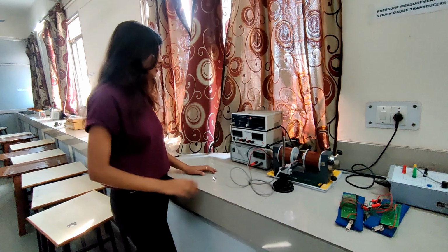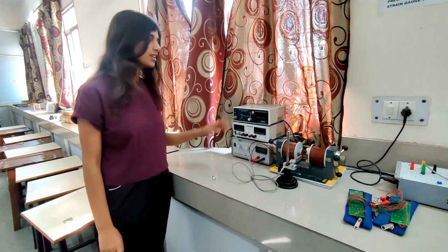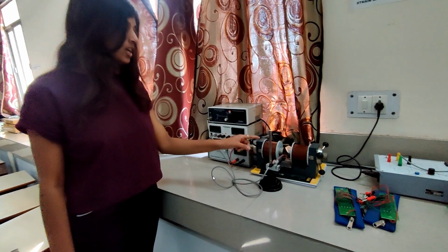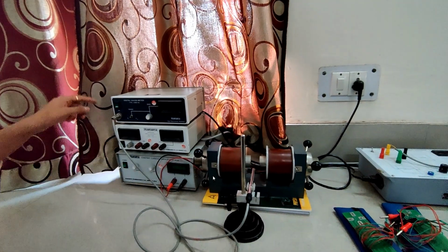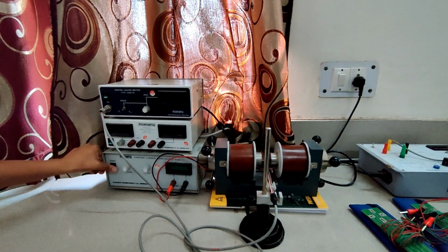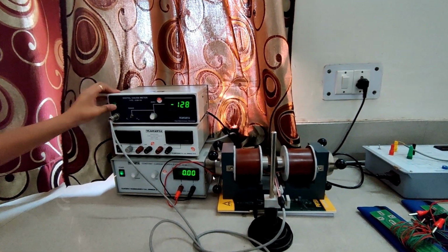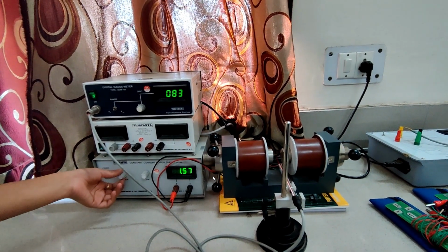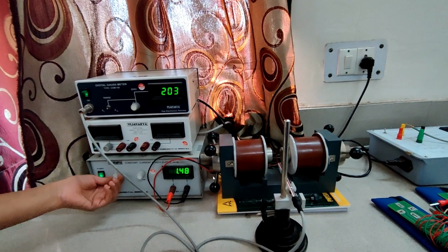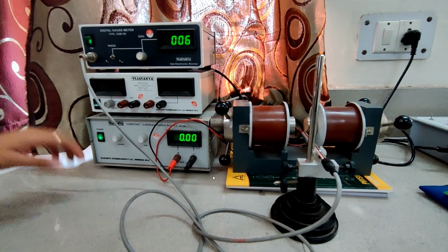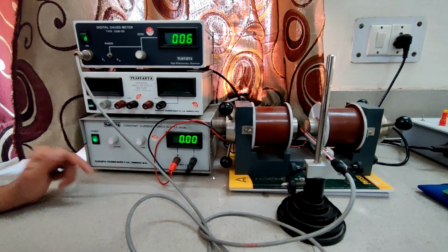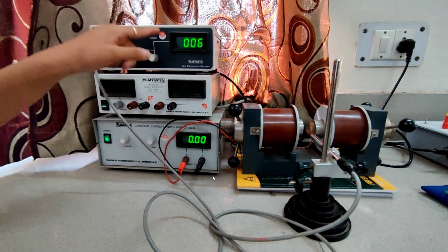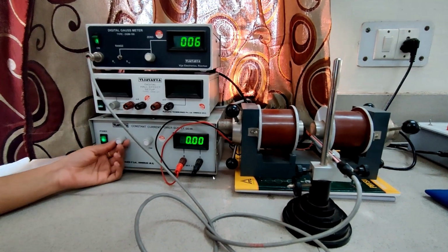supply. So in the first part of the experiment, I will study the variation of magnetic field with changing current, and for that I have already inserted the Gauss probe inside the electromagnet connected to the digital Gauss meter. So I will turn the constant current power supply on and digital Gauss meter on. So as we can see, as the current increases, the magnetic field also increases. So now I'll increase the constant current power supply using this knob in steps of 0.5 ampere to study and record the corresponding magnetic field in the extended range.